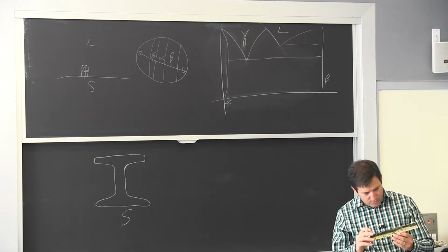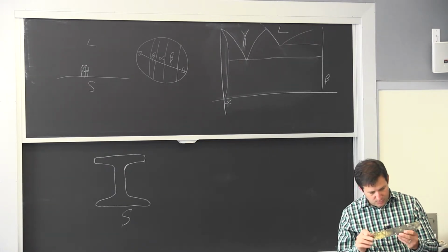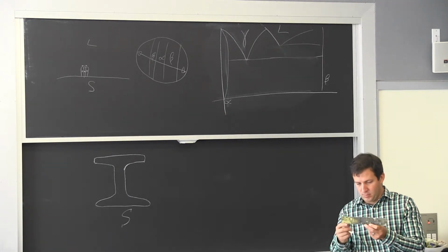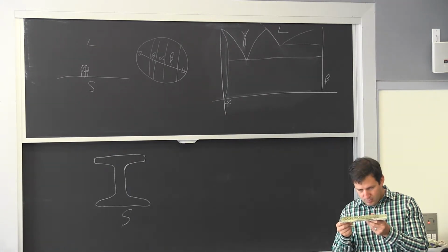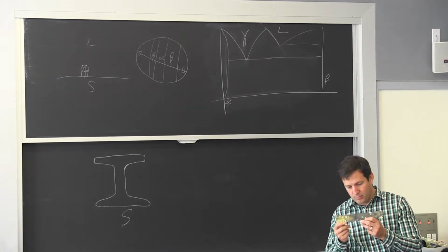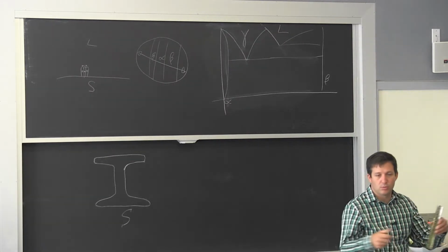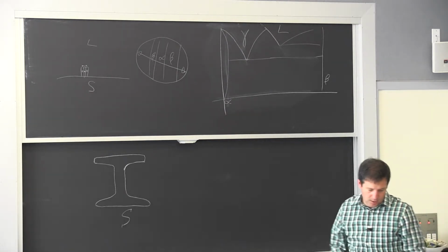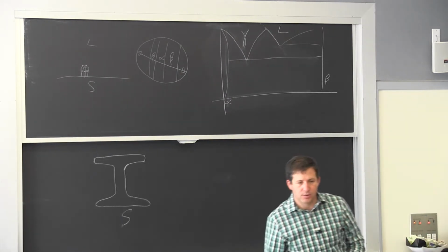There are a couple interesting things to it. One is you'll see some elongated holes. These are not from the drilling process. They are from loose rivets that just grew and extended the hole. And when you lost the support, you had a break on one side, so there's actually a fracture surface on this side here. Because you lost support, so you had bending. And this was intended to be really tension compression.